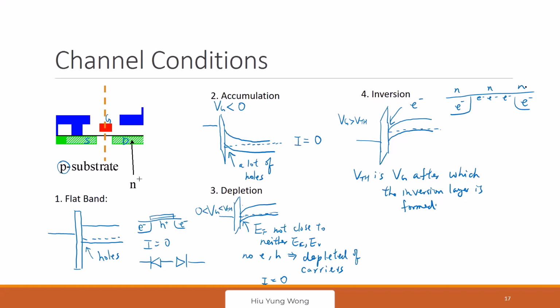I'm sorry I spent many lectures going over the basics, not because I'm a device guy. It's because if we want to understand the capacitance, we need to review all this device physics. Now you understand, after I form the inversion layer, I have a continuous channel here. Then what is the change of the capacitance between the gate and source drain? We will find out. Okay. Any questions?